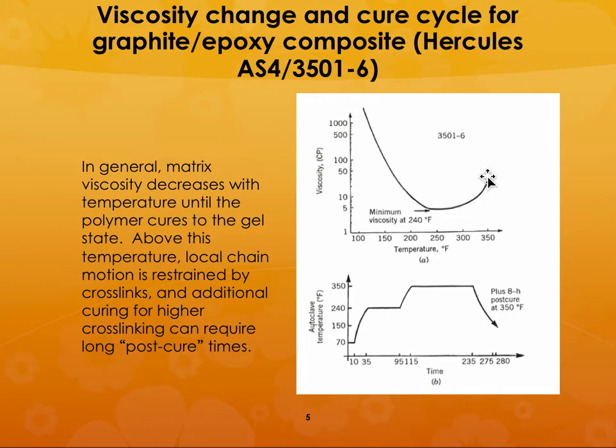So the viscosity goes up exponentially beyond a certain point. So you want to limit your curing temperature, in this case, to about 250 degrees Fahrenheit, so that you can have the lowest viscosity possible, so you get the maximum efficiency of fill into the composite material.